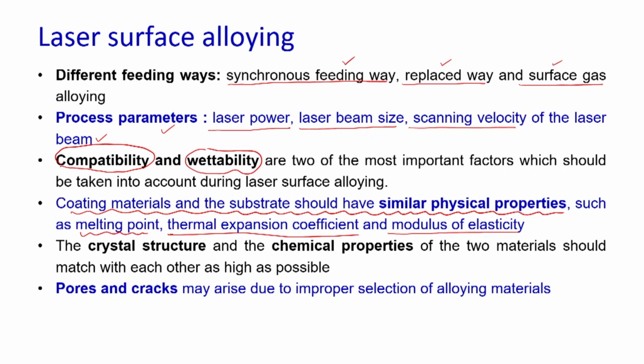They should not be exactly matching. However, there has to be certain agreement between the properties of the deposition material and the properties of the substrate material. So, their melting points have to be near to each other, and their thermal expansion coefficient and modulus of elasticity should be matching.